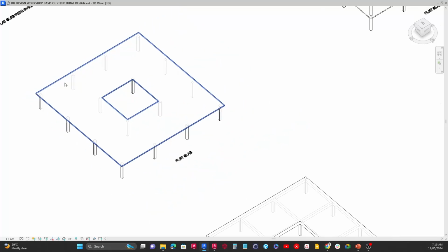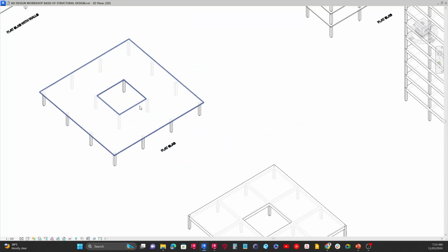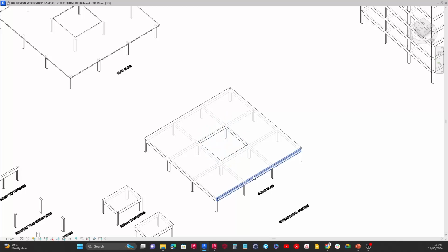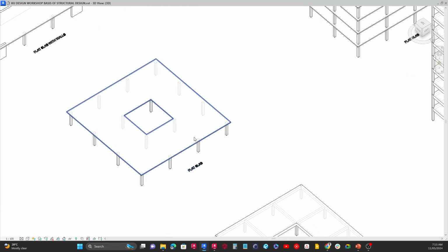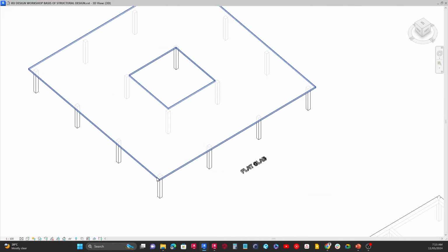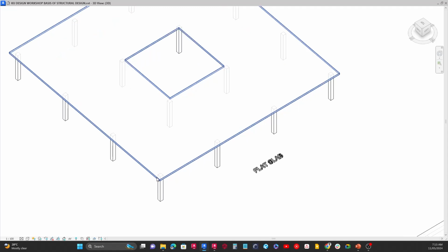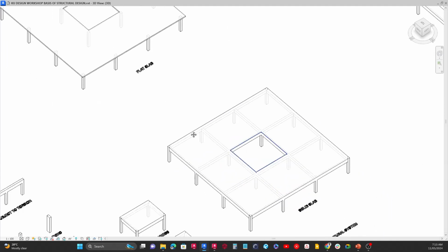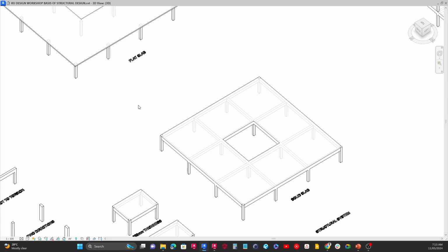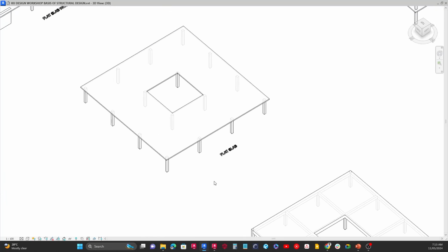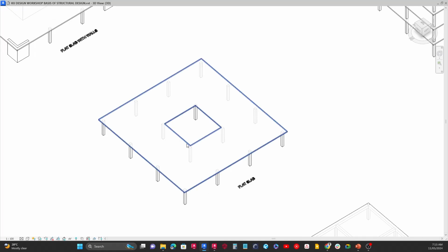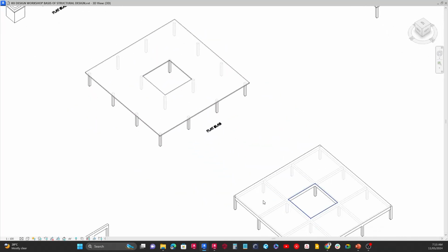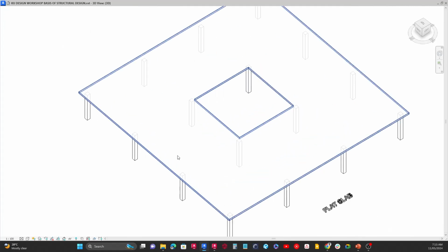Now you will probably be wondering, why would we have a simple system and still have a solid slab system? In most situations, when you're using a flat slab, it's going to require the slab to be thicker. A thicker slab is going to be more expensive, so most of the time it's better to opt for a solid slab. A solid slab will also make the structure a little bit more rigid and better able to resist loading, especially in a seismic prone area. That means earthquakes and all of that, or winds. So in that case, a solid slab may be better as well.